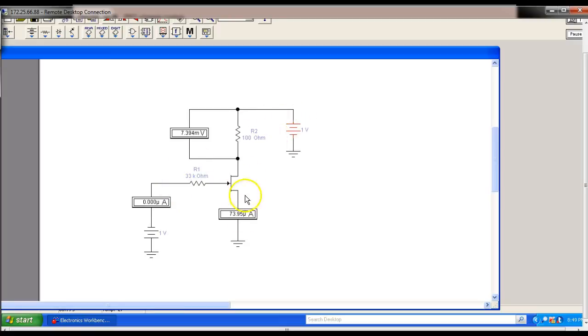Below the pinch-off voltage. So to operate this guy as Class A or in linear mode, we're going to make sure that we operate this thing with a voltage drain to source that's above what we call the pinch-off voltage. And where do we find this information? Well, we find it in the data sheets for the FET. And we're going to look at it. I think we're using a 2N5857.